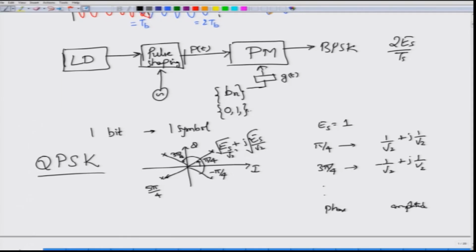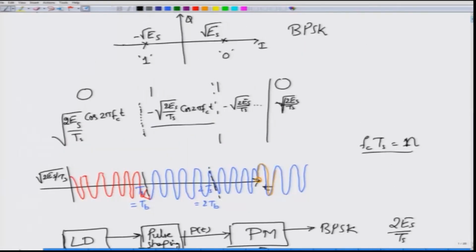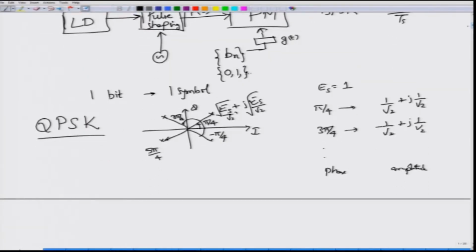However, there is one thing that we have not yet done. Remember, in the BPSK modulation that we had taken, if you go back to the constellation, you had constellation points, which are simply some numbers in the IQ space, and they had to be mapped into the corresponding symbols. BPSK symbol is equal to bit. In this particular case, you have 4 such constellation points, and you can map them to 2 bits per constellation point. So, I can map this as 00, 01, 10 and 11.